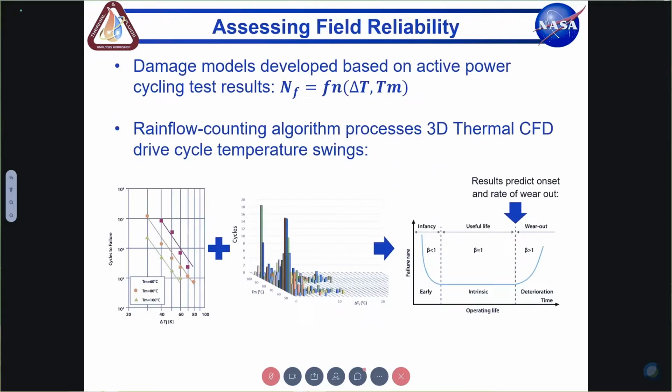If you keep on cycling, this region gets longer and longer, which shows an increasing die attach void, which is basically leading to the ultimate failure of the component. So you can understand what's happening, at which cycle number, and you can either select a different component or change your design.